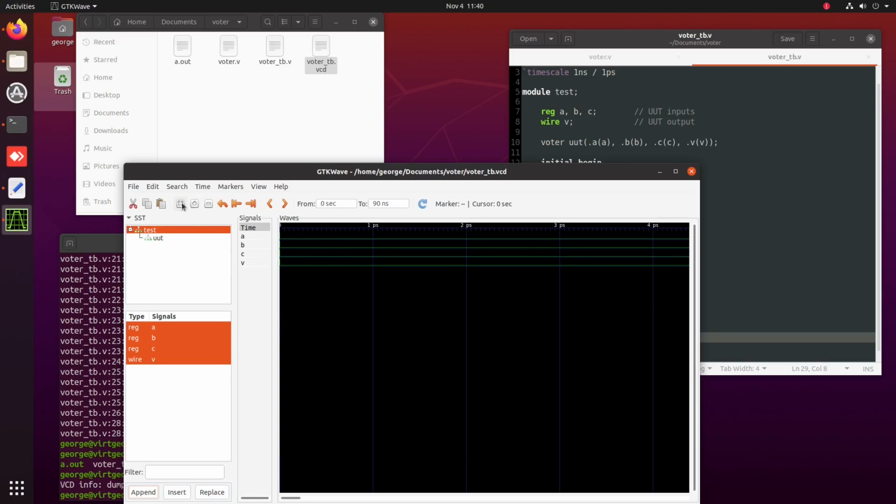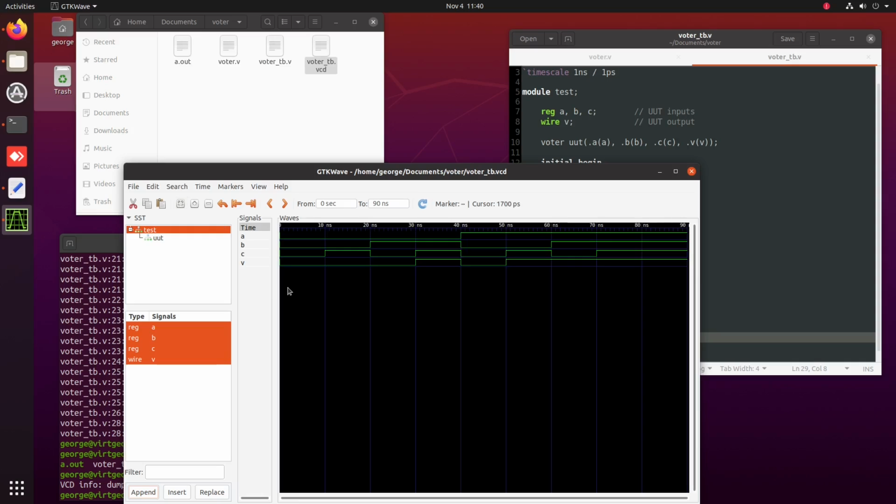Once we do that, we use the full zoom button here to see all the signals at the same time. So here we can see if we have done it correctly. I think so, because you see our outputs are 0, 0, 0, A, B, and C. C changes to 1, 0, 0, 1, 0, 1, 0. You can click with the cursor here and check the values.